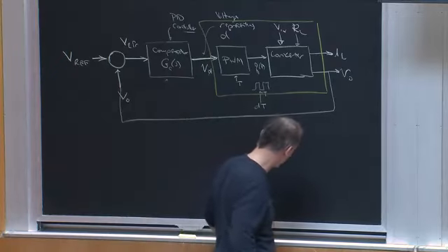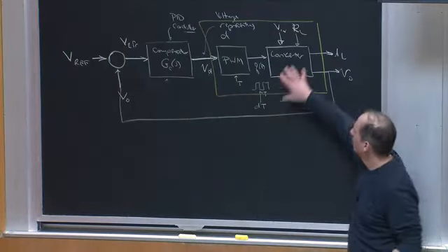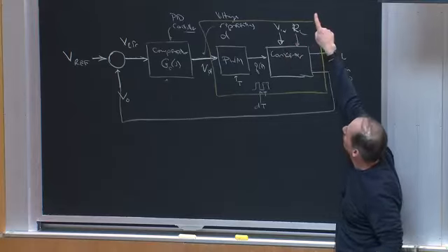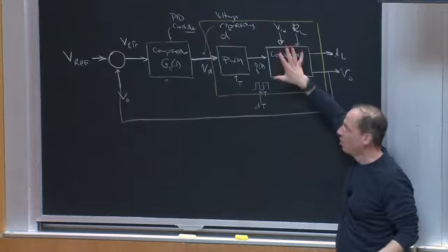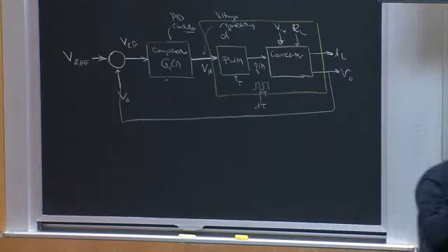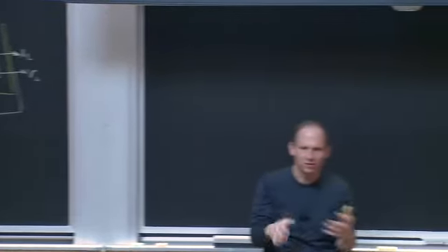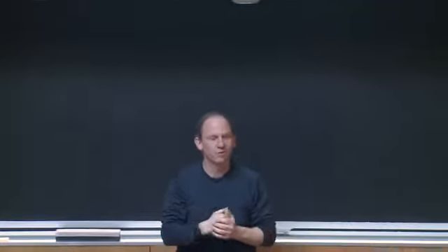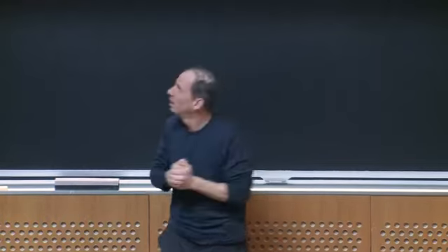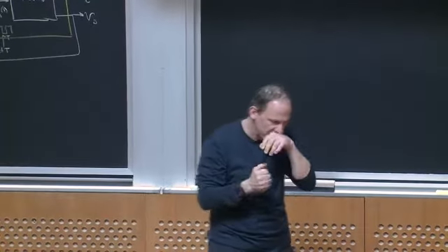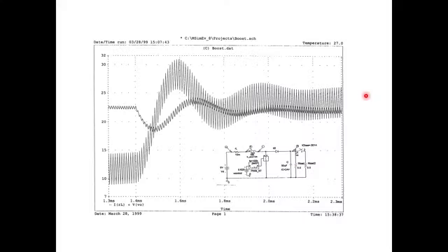And so what I'd like to talk about is how we build this dynamic model, instead of a periodic steady state model. What does the dynamic model of this thing look like, from variations in duty ratio, for example, to the variations in the output voltage? Coming back to this picture, we can see that what we have here is a bunch of switching. Here's the switching ripple, the triangular ripple current in the inductor. It goes through some oscillations, and then it settles down. And the same thing with the capacitor voltage.